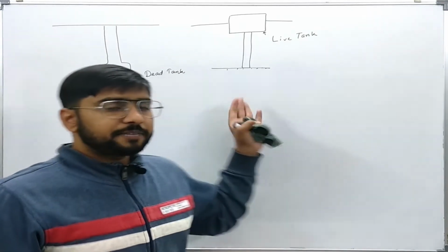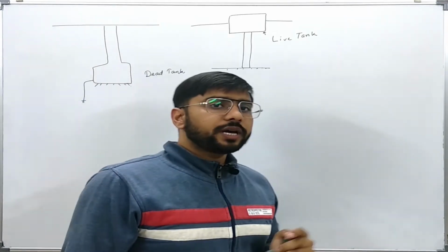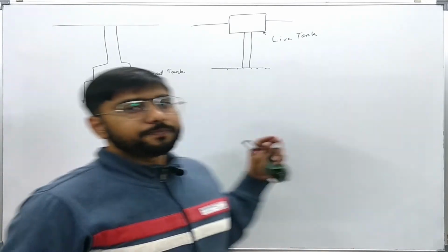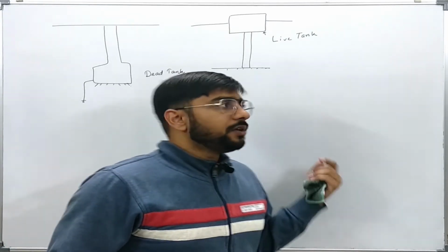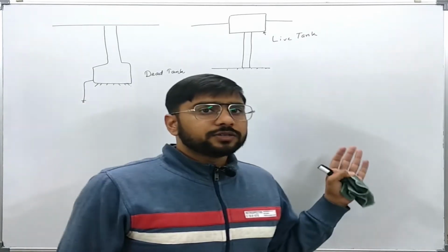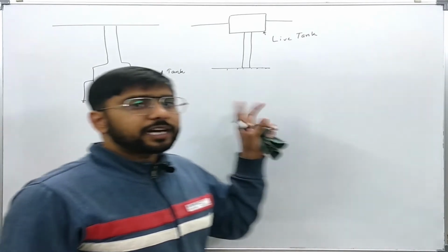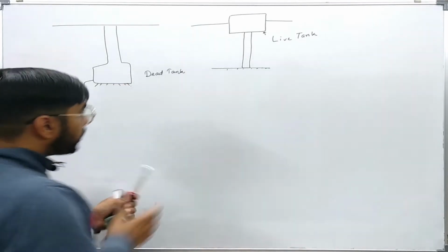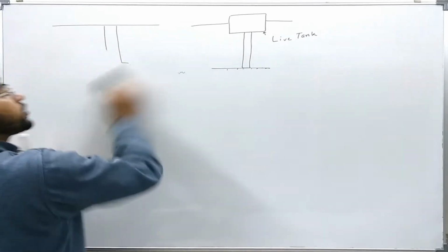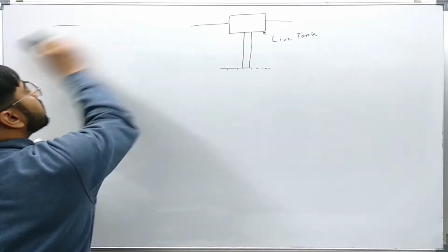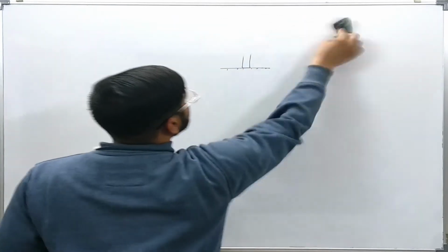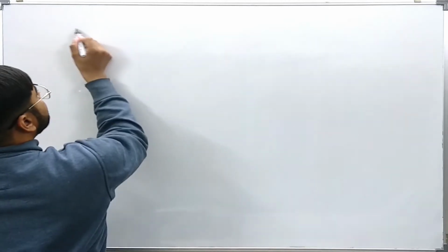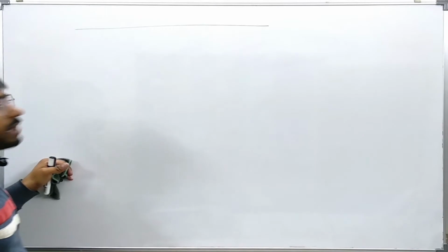Each kind of CT has some benefits as well as some disadvantages. Depending upon the utility, the cost involved and the space available, we can opt for any kind of design. So this is usually taken care of while designing the system. Now, what is the meaning of current transformer if we want to make an equivalent circuit diagram? Usually we show that the primary is just a single wire, or it may have one or two turns according to the design.